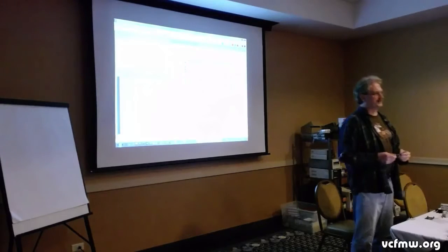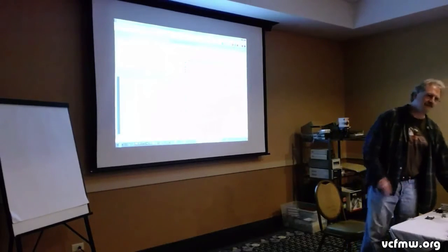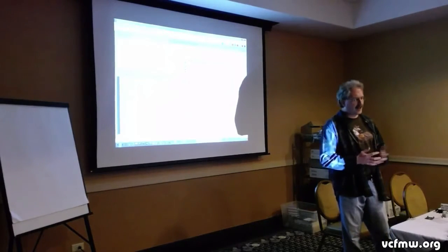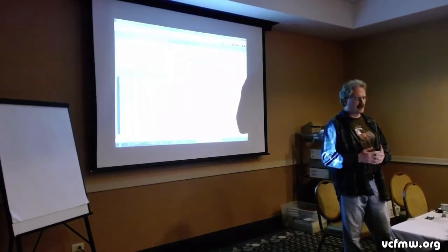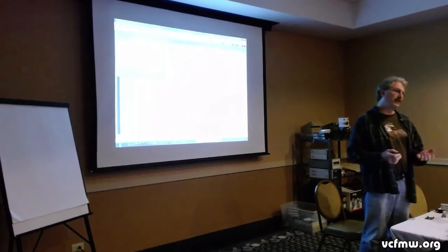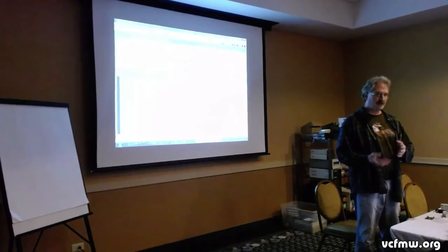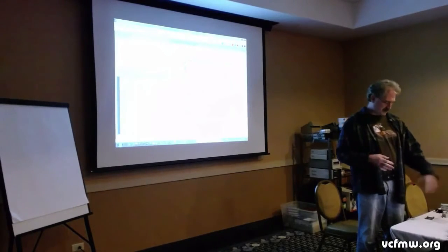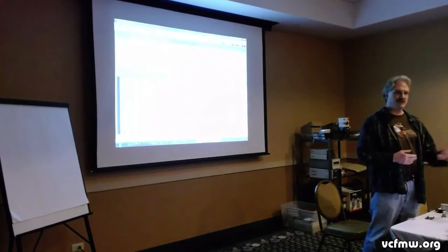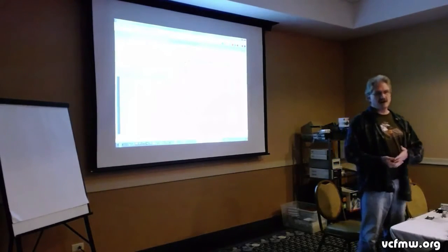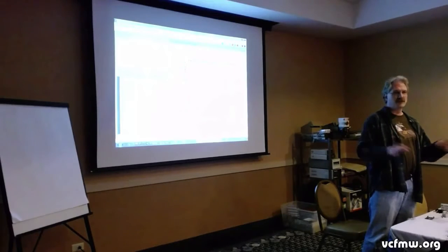So, any questions? Yeah, 5-volt versus 3.3. 5-volt, right now, you can't. There are a couple of manufacturers that still make 5-volt CPLDs. Most of the things you're going to find are 3.3 volts, but they have 5-volt tolerant logic. That's probably the most prevalent. The Xilinx parts that I'm using are 3.3 volt units that will handle 5-volt I/O, which still works okay for most of our platform.